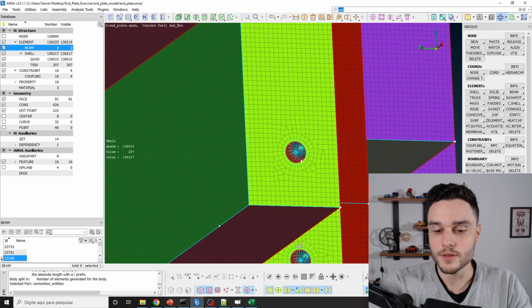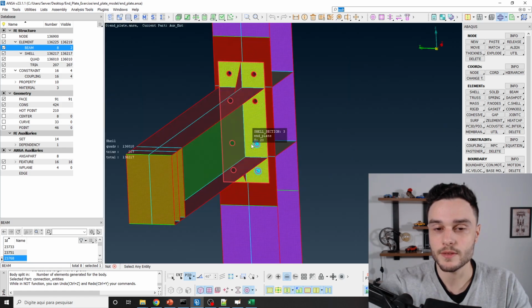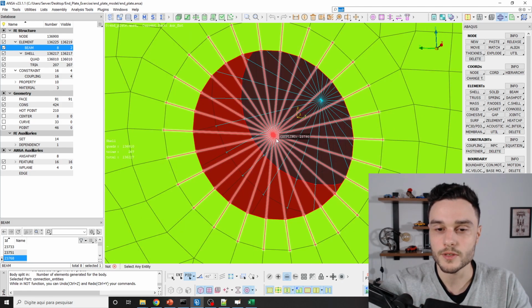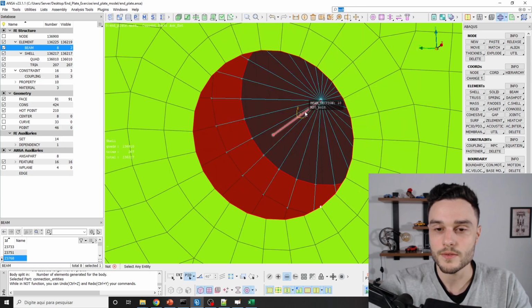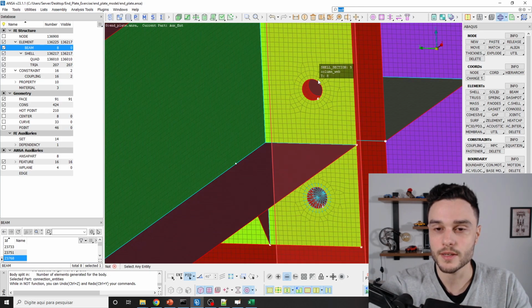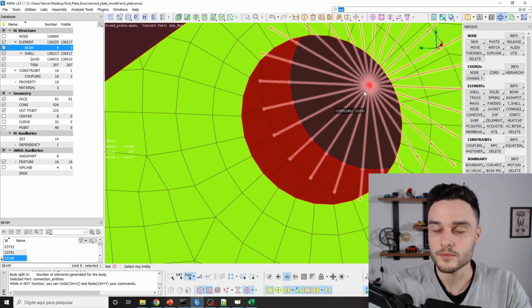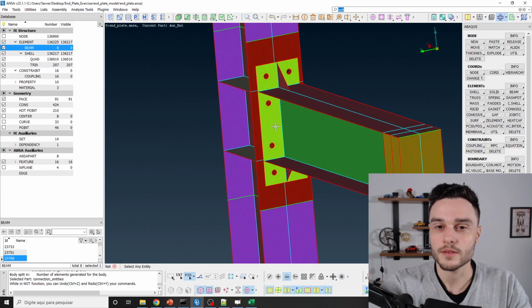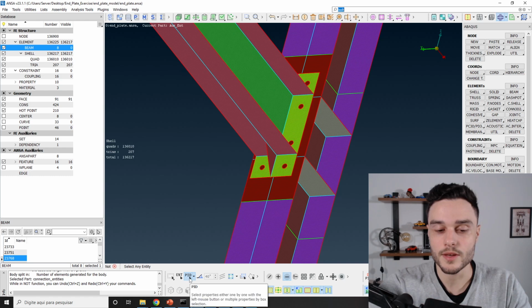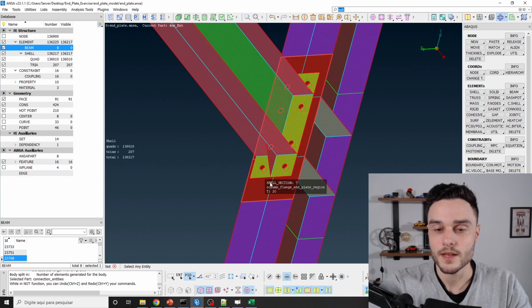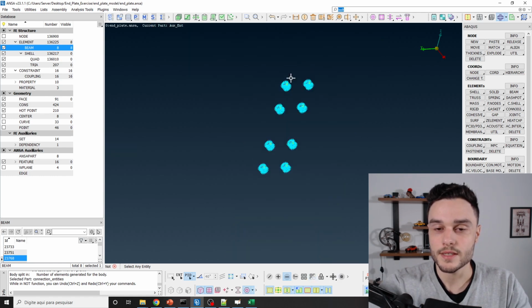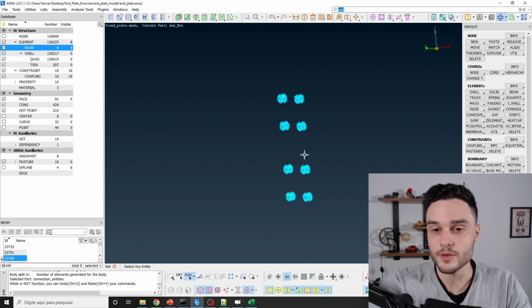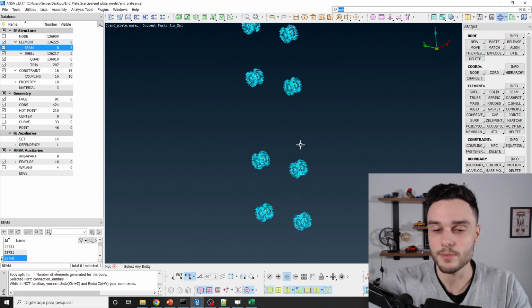And then I'm going to use this tool here, not. Not is to hide some specific entities. I'm going to zoom in, and I'm going to select this coupling to hide, this beam, and this coupling to hide, and also this one, this one. And by the way, the selection mode here is property ID. And then after doing that, I'm going to click here again in invert. And now I have everything that was not visible, which is these couplings and beams.